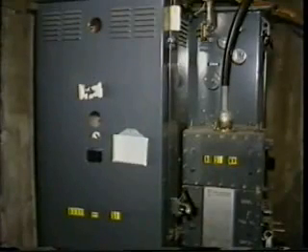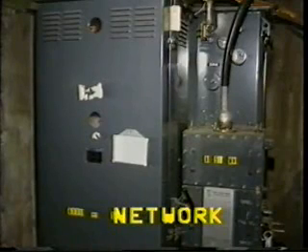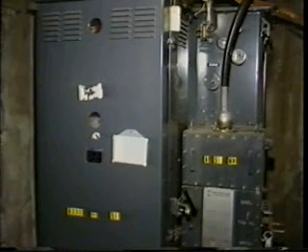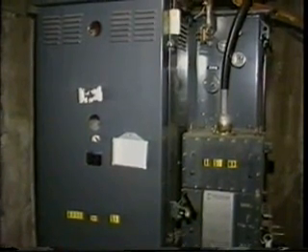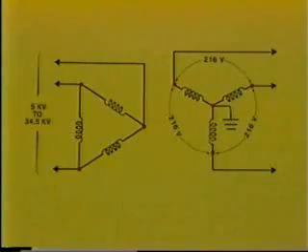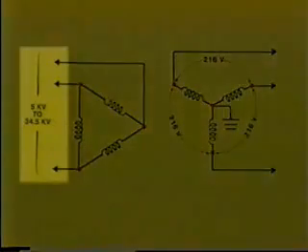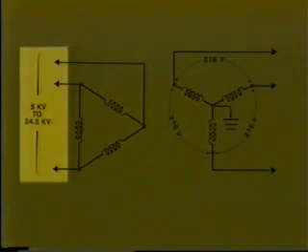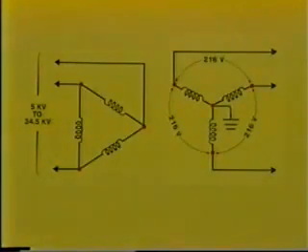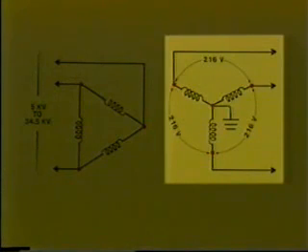Another type of transformer sometimes installed underground is the network transformer. This is specially designed to feed into a secondary network supplying a high-density downtown load. And this type of transformer is also used to form spot networks at or in commercial buildings. Network transformers are always three-phase units designed for primary voltage within the range of 5 kV up to 34.5 kV. The secondary winding is connected in Y with the neutral grounded.